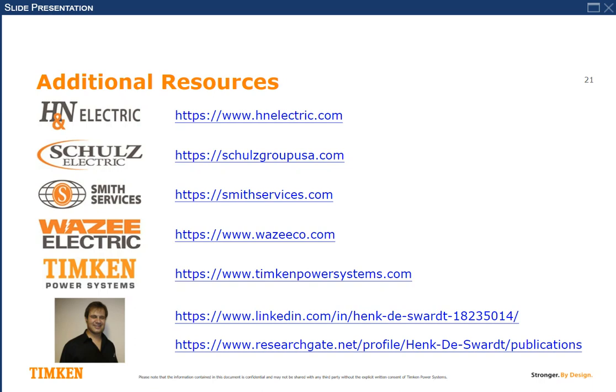The best place for resources on that would be EASA. EASA is the Electrical Apparatus Service Association, actually worldwide, and they have a really good standardized manual where they do repair recommendations, because there is no IEEE or NEMA standard that says this is how you should do it. But EASA is really good. Over time, they've developed systems of how cores should be burned out. They've got a technical service manual that explains how it's done.